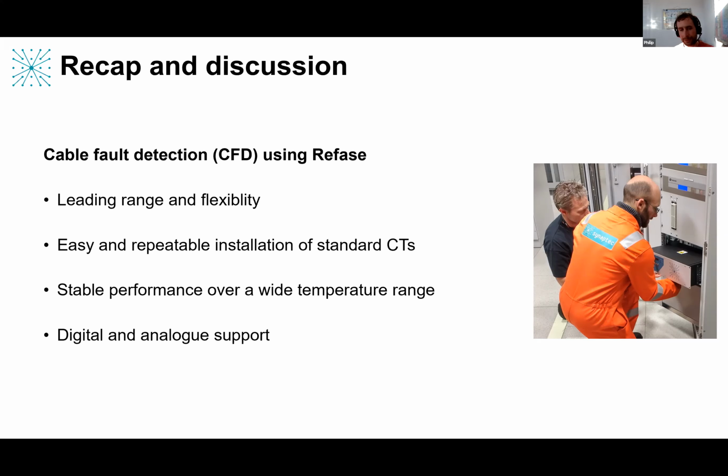Now there's a fiber technique that we build into our systems called OTDR, which is the optical equivalent of TDR. So it's reflectometry. It's looking for the time of flight of the light, which will reflect very strongly off a break. So once the faulted section has been identified, you can fire off your OTDR pulse and it'll detect your fault location to within a few centimeters.